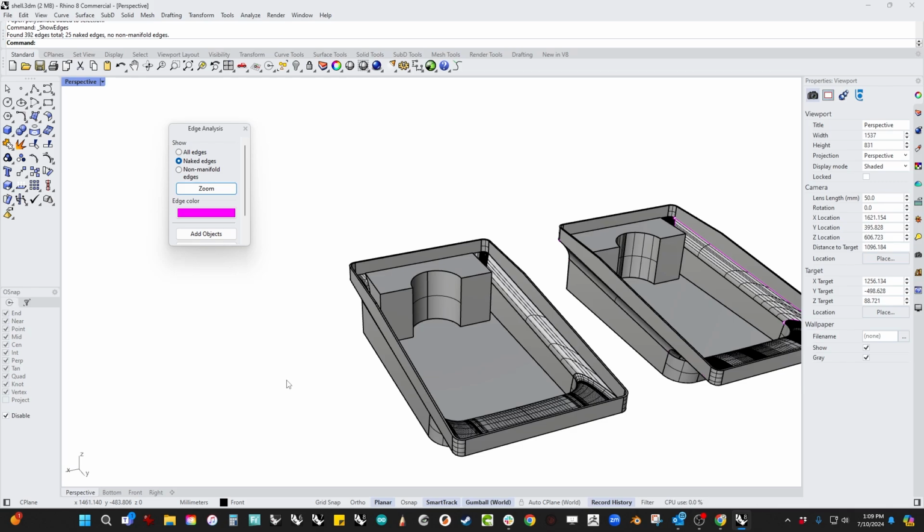And then all of those offsets get trimmed, and then they get unified, and then it tries to connect it, and then a whole bunch of stuff is happening in the background. But at the core of what's happening here, it's an offset. So anytime you get an offset that makes an overly complex surface, or the points of a surface bow tie on each other, or anything like that, those are all things that contribute to why shelling fails.